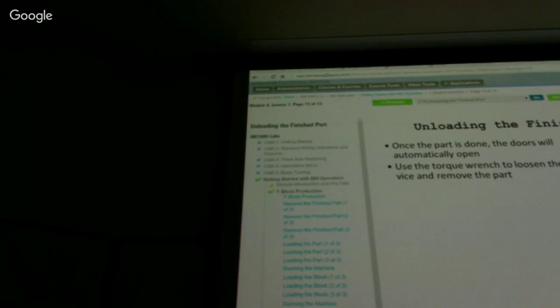And what I end up with is a surface that looks like this. A surface that would be blue if I had a blue marker. Which is what we see here, right? Ridges like that because we're taking an end mill. I think the radius is 5/8 of an inch of the bullnose end mill that we're using. So you could have an end mill that's like this. You could have one that's spherical on the bottom. So it's got a hemisphere on the bottom. Do the same thing with it.